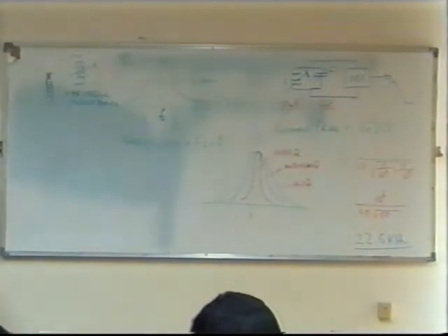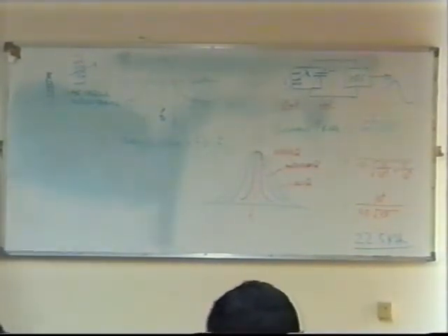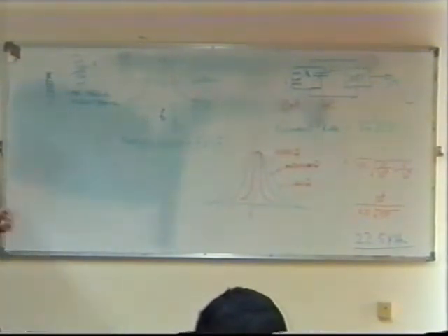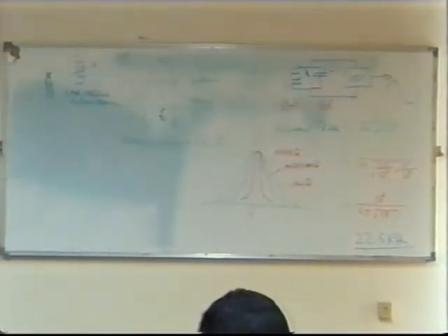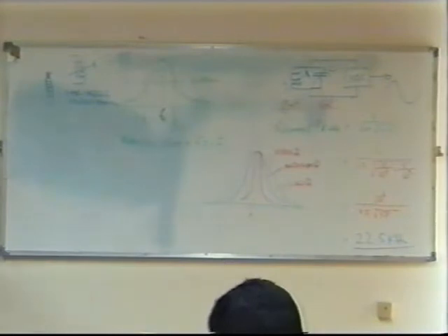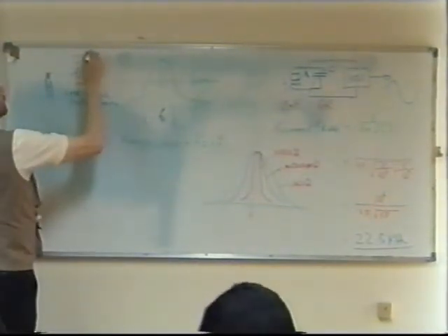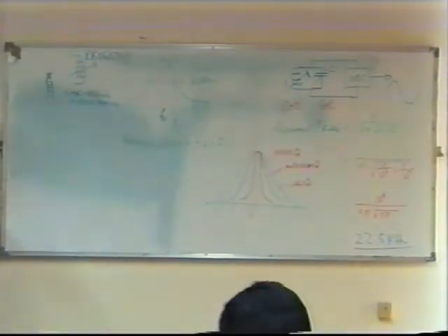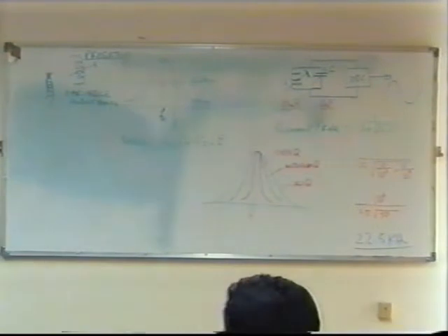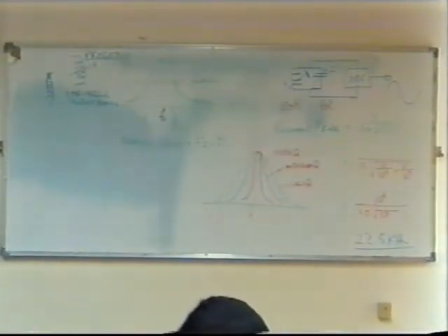Usually the circuit is designed for one particular frequency. Now, I'm not talking about tuning throughout a radio band. If that's the case, a different technique could be used. You could use a variable capacitor, which enables you to vary it by a large amount and therefore vary the frequency. But these are what we call preset as opposed to variable. It's normally set by the manufacturer, but a technician might have to change it again if something goes wrong, the radio gets damaged or a component is changed. Sometimes you need to check that again.